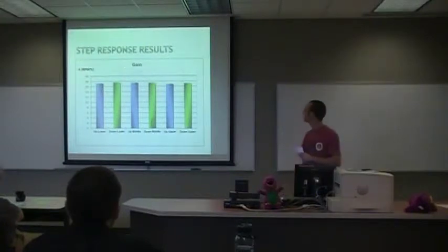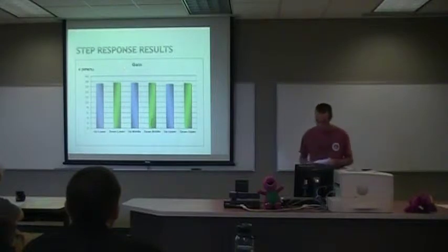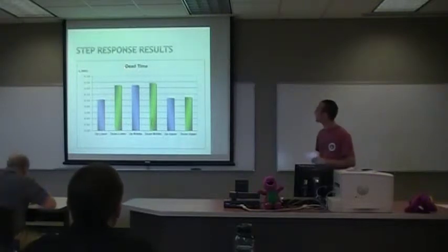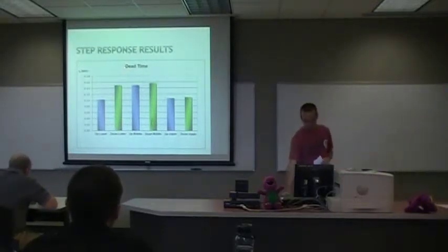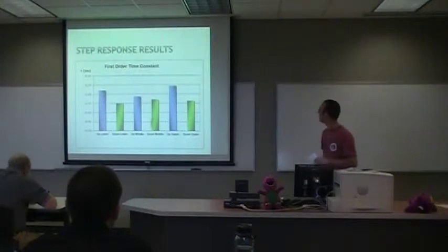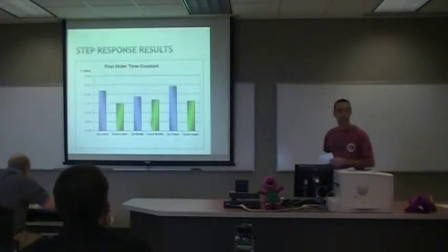And here are the step response results with a gain that's pretty consistent throughout the board. And the dead time is fairly consistent. It ranges from 0.11 seconds to 0.159 seconds. The first order time constant varies a little more, from 0.15 to 0.21 seconds.